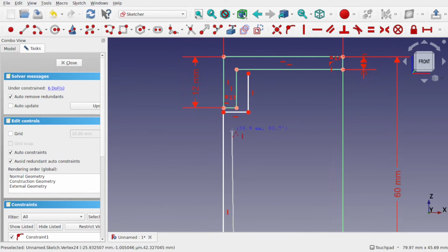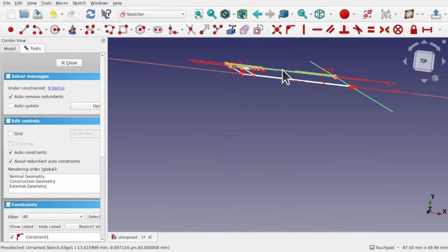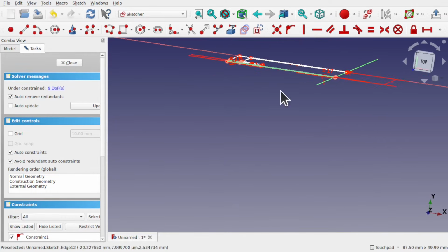Now at this point, I'm going to do something slightly different. I'm going to come right across at an angle like so, and then come up and finally connect up with this point, coincident constraint. Why did I do this? Well, this allows me to 3D print this without the use of supports. So I can set this as a relevant angle to allow me to get this into shape. It allows me to print from the bottom upwards.